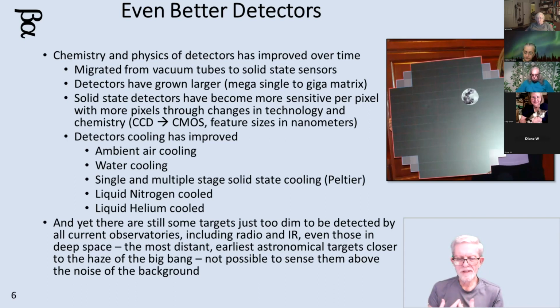There are people out there using Peltiers and water cooling, but at the high scientific level, they will liquid nitrogen cool them, or in the case of the James Webb Space Telescope, it's liquid helium cooled and liquid nitrogen cooled and uses a Peltier, and it recycles on itself. So you've got to get it as close to absolute zero as possible to get rid of all of the electronic noise that's part of the actual electronics trying to give you the image.